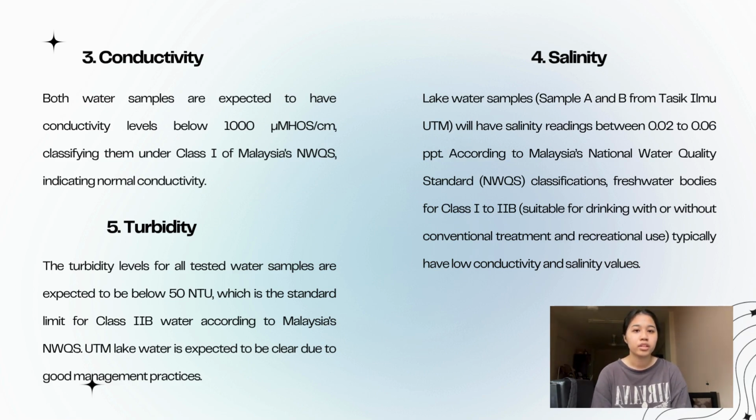The last one is for turbidity. So the turbidity level is expected to be below 50 NTU, which is the standard limit for class 2B water according to Malaysia's NWQS. So we expect UTM lake water to be clear due to good management practice.